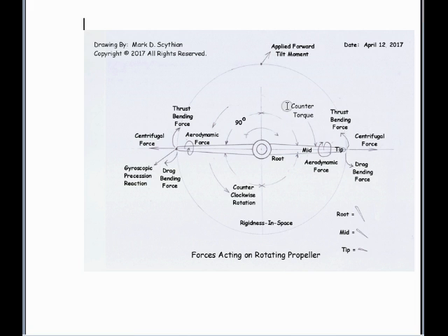But since there will be initially a counter torque moment causing the helicopter to yaw right, the pilot intuitively knows right when the liftoff and hover take place to push a little on the left anti-torque rudder pedal, causing the pitch on the anti-torque rotor to propel airflow more to the left, causing the tail to yaw to the right to cancel that torque out.